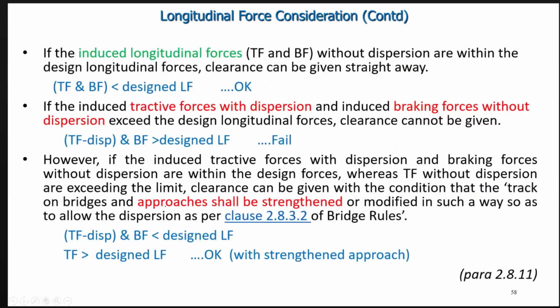So for longitudinal force design, there are 3 rules given: whatever tractive force and braking force is coming, it should be less than the design longitudinal force. Definitely this is applicable for all designs, but if the tractive force with dispersion or the braking force is more than the design, then it will fail.